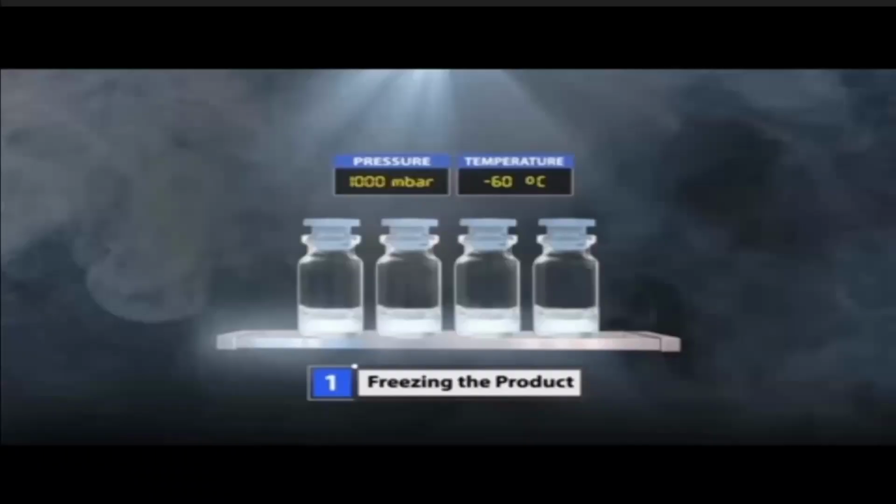Symbol of quality. So from the previous video, we can summarize the stages of freeze drying. The first one, which is freezing the product, requires the following conditions: the pressure is equal to 1000 millibar, which is equal to 1 atmosphere, and the temperature below 0 degrees centigrade, that is minus 60 degrees centigrade. These are the requirements for freezing the product.